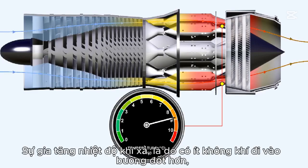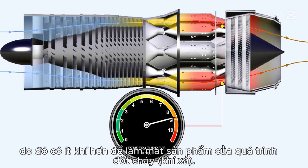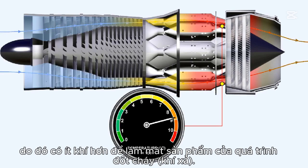This latter effect, the increase in exhaust gas temperature, is caused by the fact that there is less air going to the combustion chambers. Hence, there is less air to cool the products of combustion, the exhaust gases.